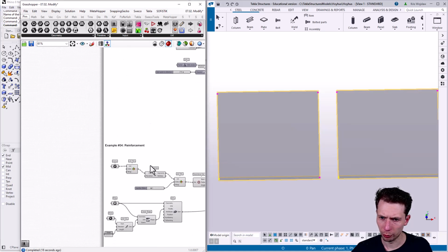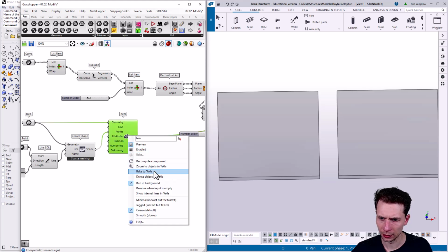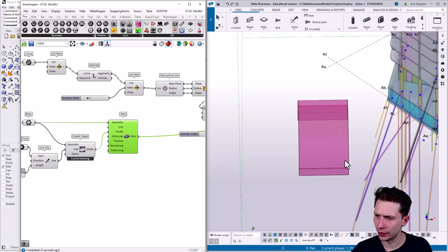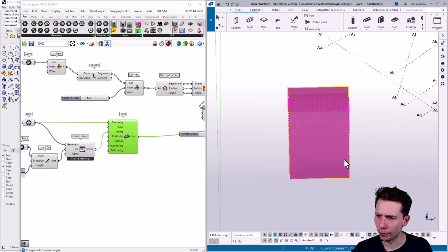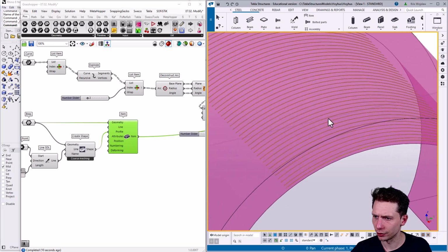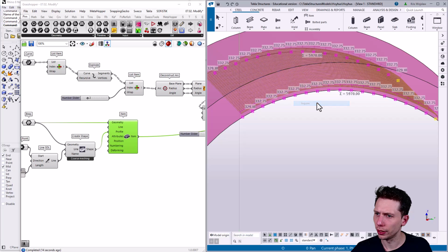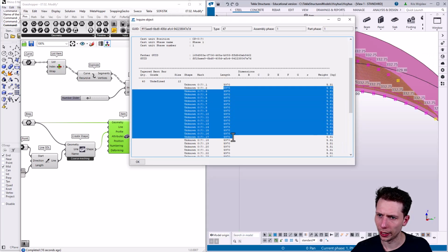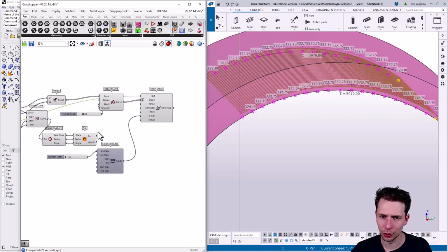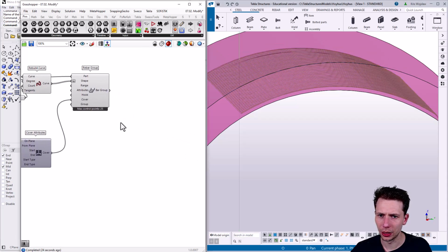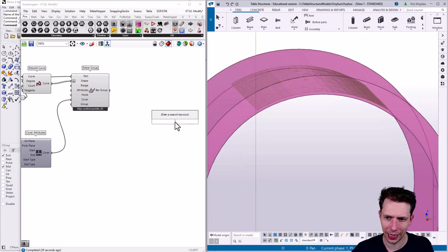Next example with reinforcement. So here it's a reinforcement from the tunnel. So let's zoom into Tekla, so I can just show only selected. Just a reminder, here we have the curve reinforcement placed with some offset, and if we go to inquire, we can see that we have the same length, sorry. And our aim is to create it a little bit longer on one side, so they will be with the tapered form.